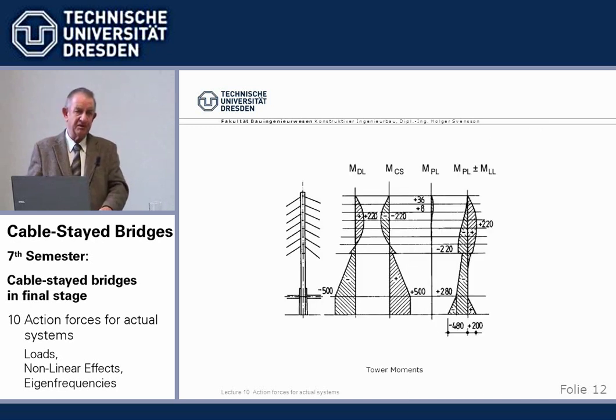Same for the towers. We can, by pulling at the cable, say that we use the forestays for the beam and the backstays for the tower, to have sufficient statically indeterminate units. So this is the run of moments under permanent loads. It's fixed, which is on supports here. These are the moments due to cable shortening.